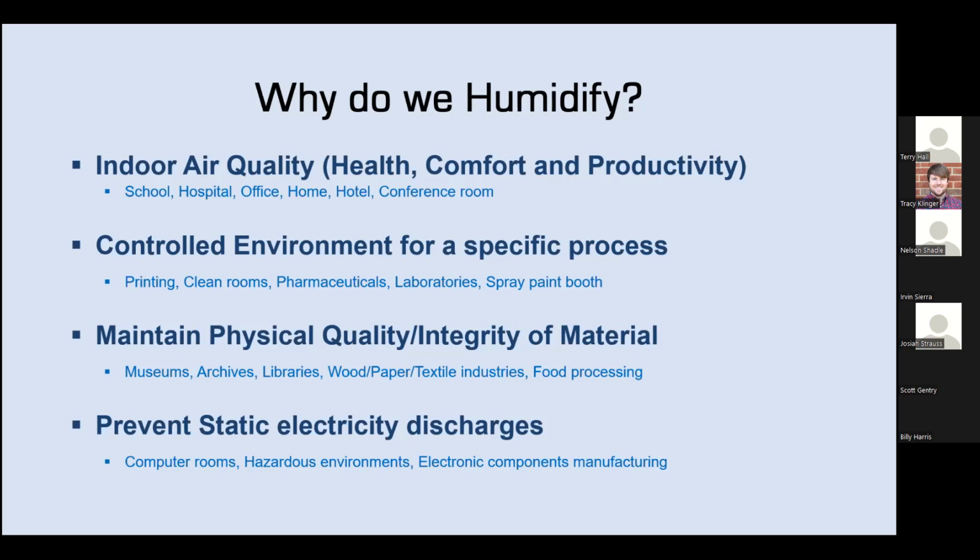It's called the Granite Mountain Vaults, and they need humidification in there, even though it's a small load, because you don't have a lot of air exchange. You still require humidification to maintain the integrity of all the materials and the data centers they've put in there. So it ranges from that to things where you may have more air changes.